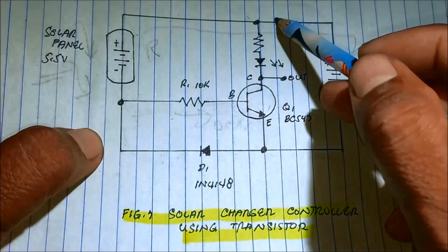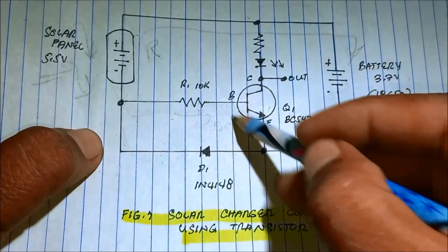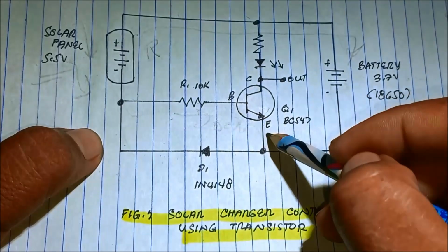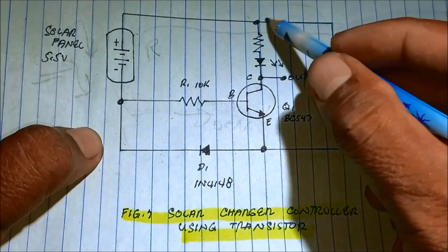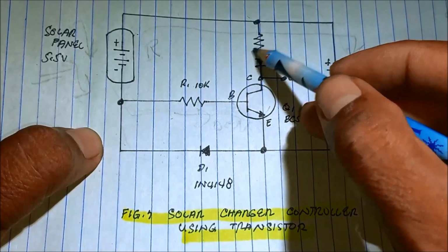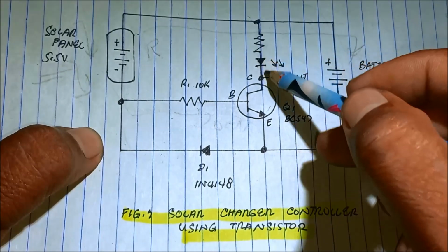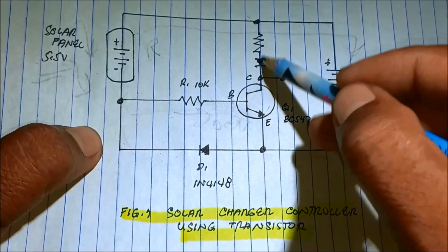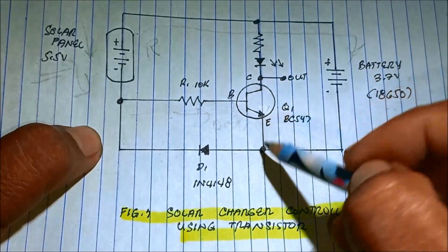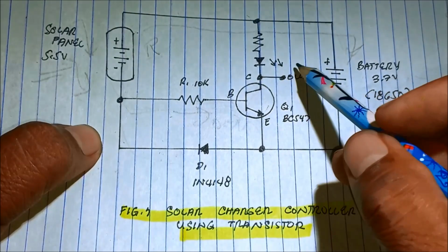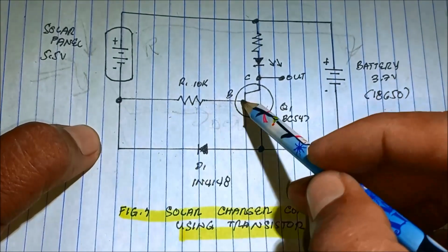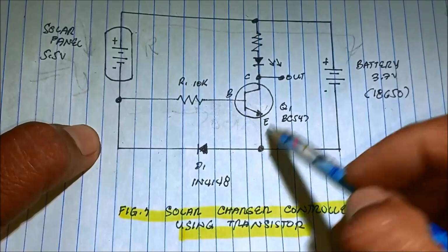And now, when there is a voltage developed across base to emitter of at least 0.7 volts, the current now flows into the LED resistor. We need this in order not to damage the LED, and then collector to emitter, then to the ground. So the LED turns on whenever there is a triggering current to the transistor.